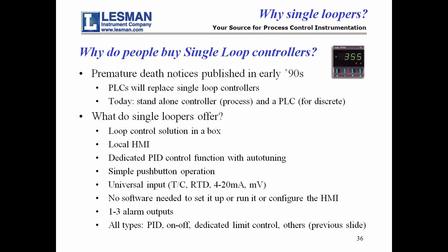And the question is why? Well, it's because of what single loopers offer. It's the loop solution in a box. You get your local HMI that doesn't have to be programmed. You get the dedicated PID functions. It's basically simple push-button operation. Changing the set point is a breeze on any of these.